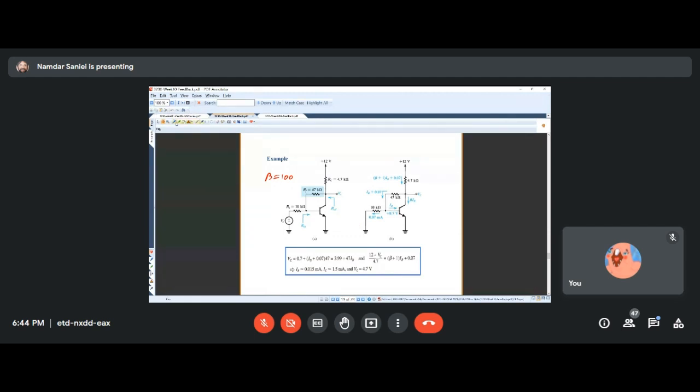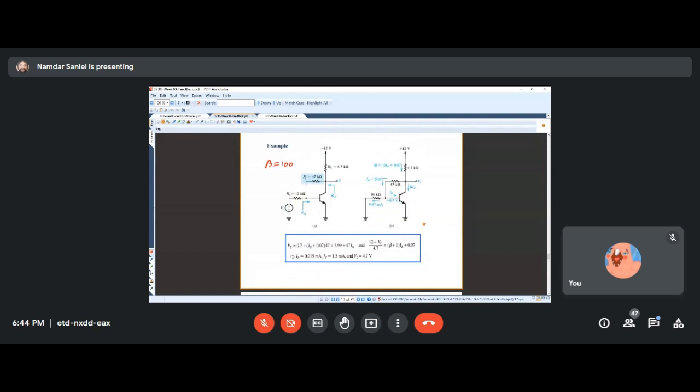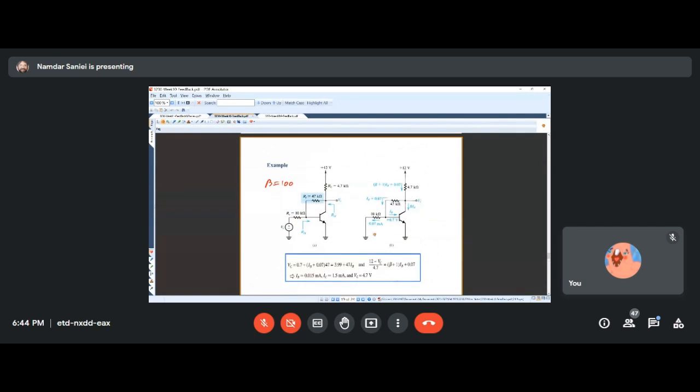Let me see if I can. Yeah, here it is. So ignore this short. A line which is connected to ground down below, and the RF. This is the two-port network of the feedback network. So we realized that, but before we get to that, we had to do some DC analysis on this circuit.